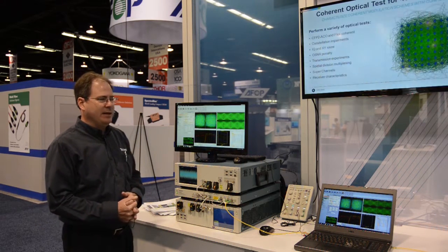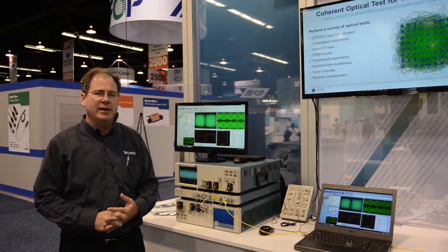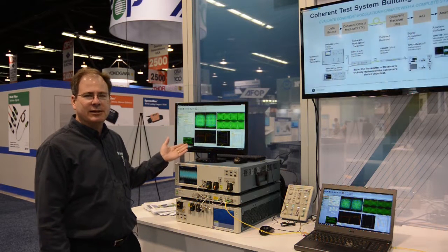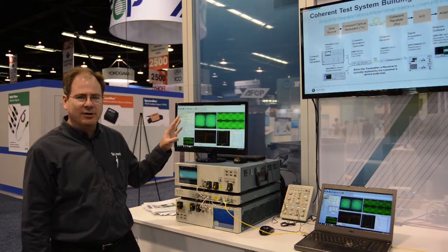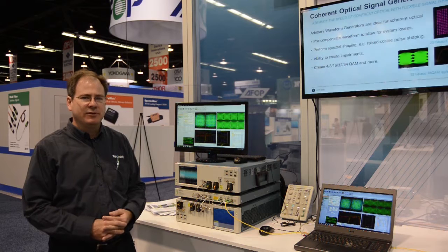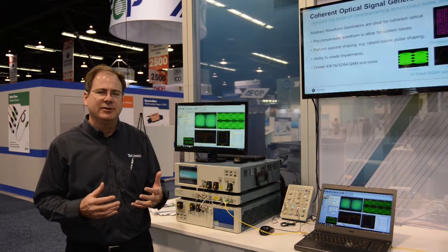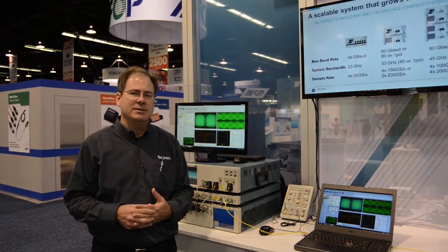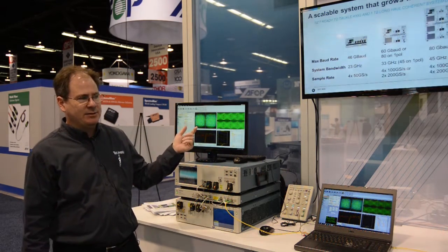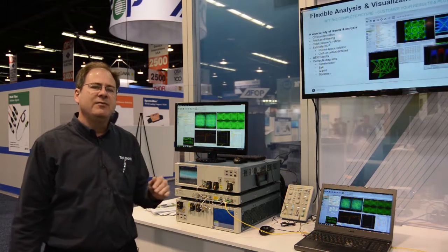The transmitter produces approximately 6% EVM for the 16 QAM and 64 QAM optical signals. With that EVM level, you wouldn't be getting such a nice constellation. What's new here is our newest version of our analysis software has some very powerful receive side equalization filters. These filters can be used to show just what is the origin of any sort of impairment to the signal by removing all frequency domain impairments so that all that's left would be impairments due to noise or nonlinearities. So we have that adaptive filter turned on, and that's giving us this nice 64 QAM constellation with an EVM of 4%.